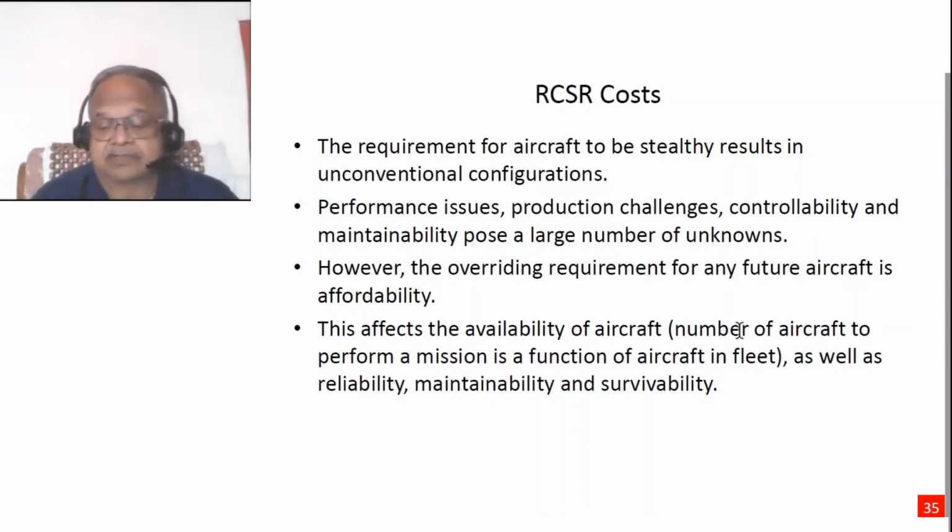So this leads to a huge increase in cost, and production challenges are also there. And because of the loss of the vertical tail, controllability becomes a problem. Of course, most of these are bombers, which are not expected to get into any kind of dogfight where they need a very high sustained turn rate and instantaneous turn rate. So it's okay, because most of these bombers are escorted by extremely agile fighter planes which take care of that. However, controllability is an issue which needs to be addressed.